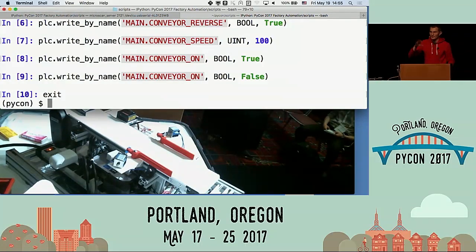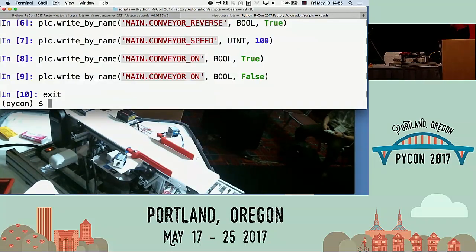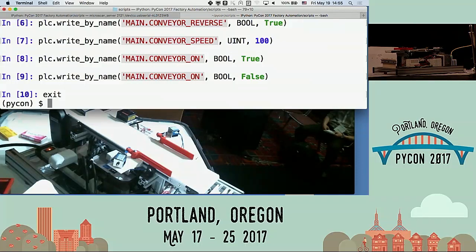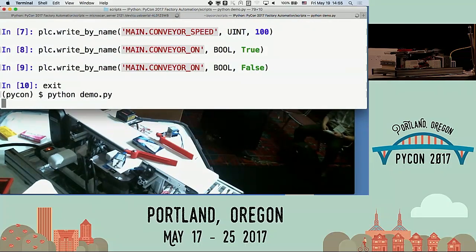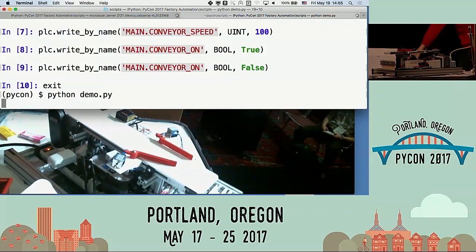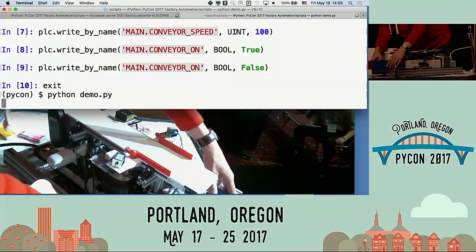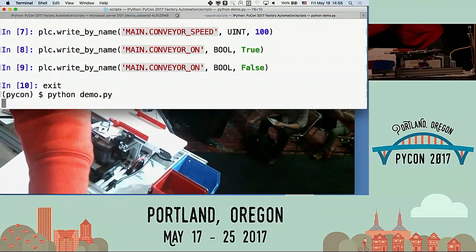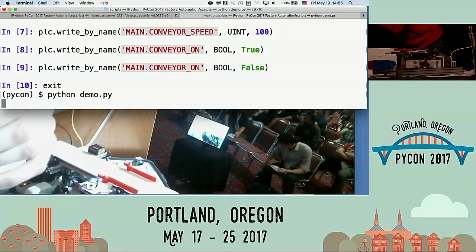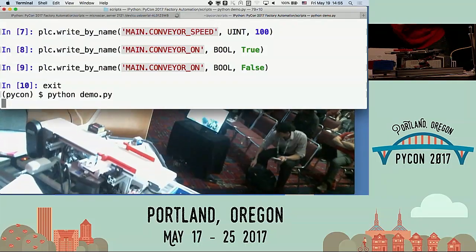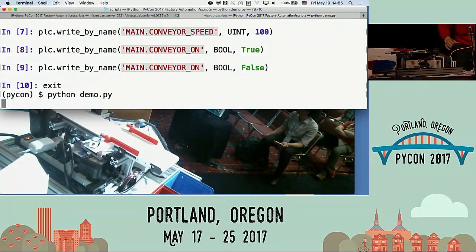We already got that XML RPC server running that's telling us the barcodes, and we're talking to the PLC over the network, so there's no direct to machine communication going on from our central server. It's all happening over the network. So we got the barcode, it scanned it, and it's sorting it to the right side. Guess who forgot to put the little trays here that catch the chewing gum? See, that's perfect setup. Let's just run a couple more down.